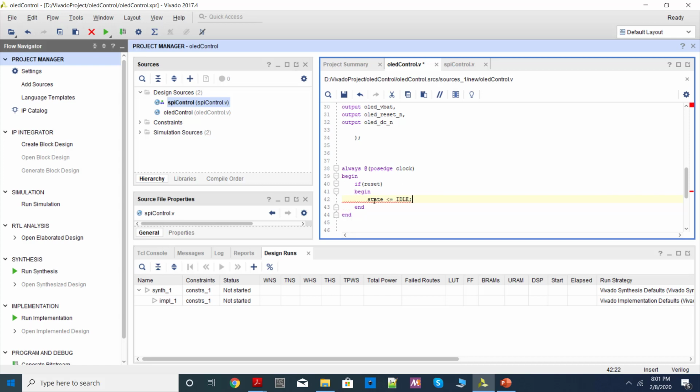Now you need to declare all these registers as well as this local parameter. So we will declare it towards the end, because if I want to know what should be the size of the state, which is basically a bunch of flip-flops which will store the current state of the system, I need to know how many states are there, so that it will be log to the base of 2 number of states. So at this point I really don't know how many states are there. So we will add the states and finally find out how many states are there, then we will declare state. Anyway, we'll have to declare it at some point of time, the size. And okay, reg state, I'm just declaring it, and the size we will change as we go along.